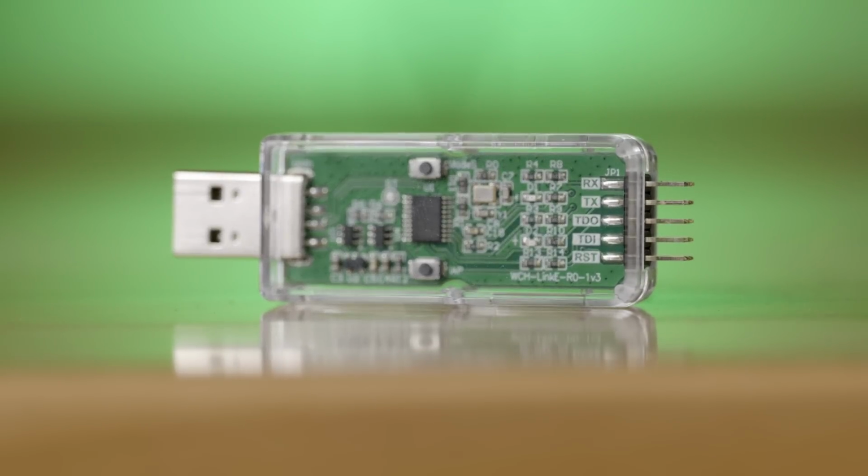I also believe RISC-V is an important development that will have a really positive impact on the industry. But from what I've seen so far, I don't believe that RISC-V microcontrollers have a really substantial edge over ARM devices. At least not yet. For one, the CH32 is different enough that you'll need different software and different programmers, and that adds to the cost, and it can have a fairly steep learning curve. And despite not requiring royalties, RISC-V parts don't seem cheaper, at least not for the parts I'm comparing here, but I'll get to cost in a second.